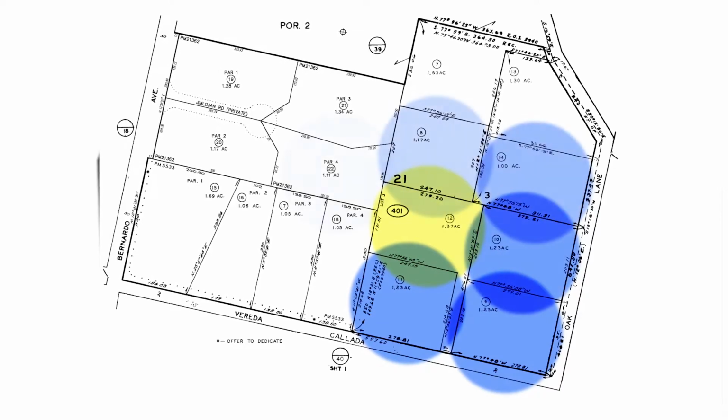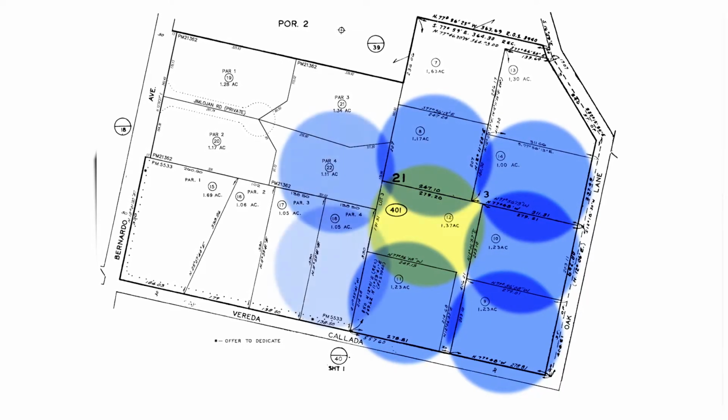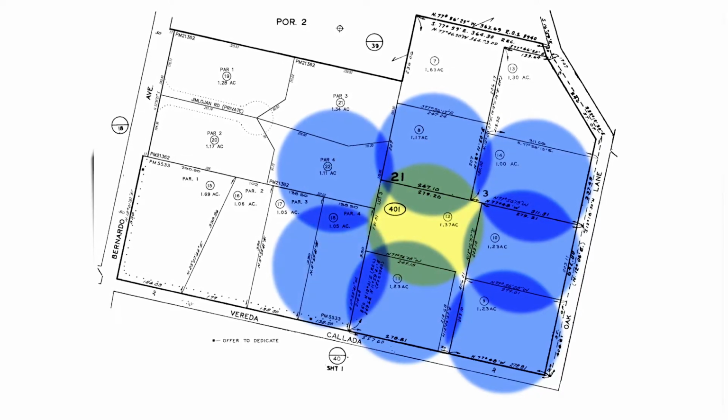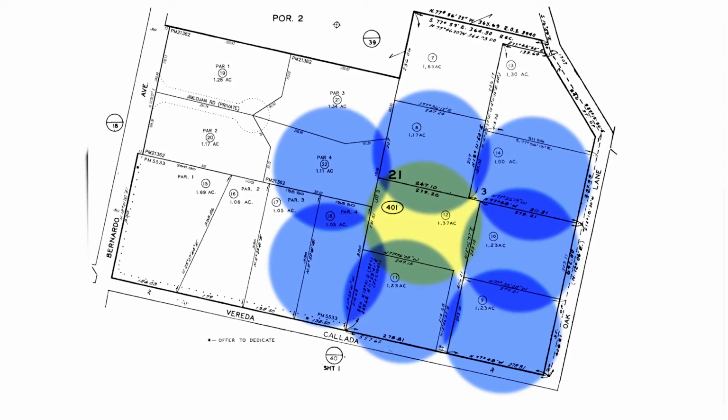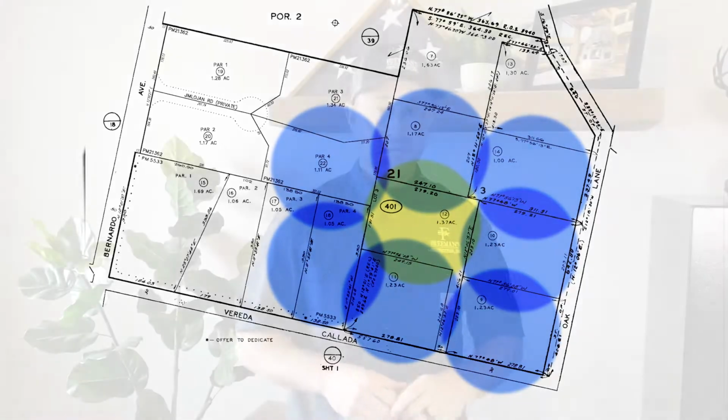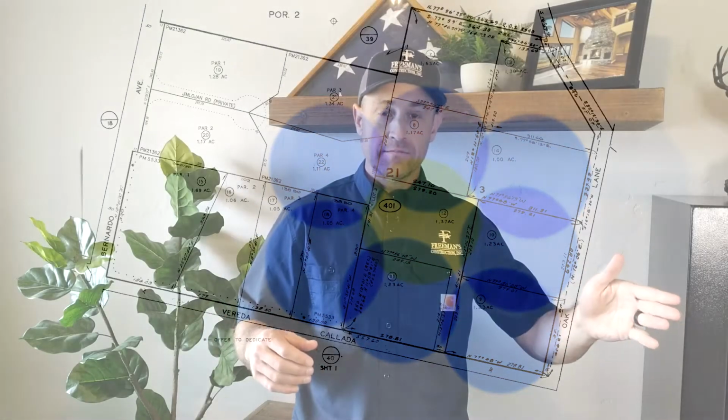They're similar soils. They will look at what the perc rates were on the adjoining properties, and they'll take the worst case perc rate. Say one was 40 and one was 20, they're going to take the 40, and then they would typically allow you to move forward with a system designed for a perc rate of 40, and you would not have to pay to have a percolation test done.